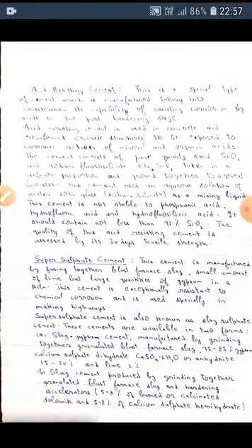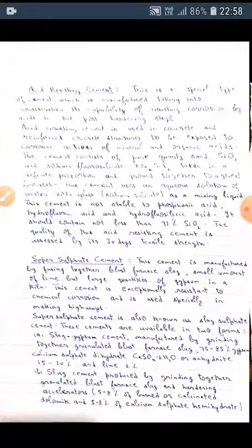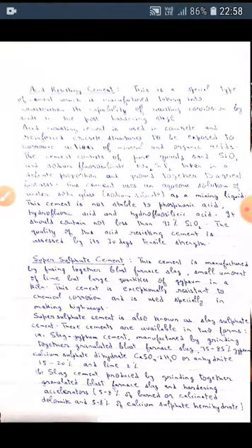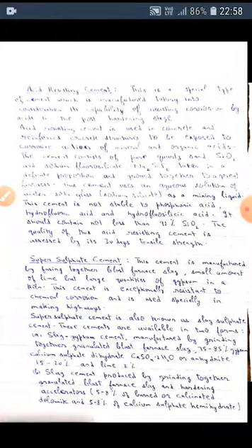The second form is known as the slag cement without clinker, produced by grinding together granulated blast furnace slag and hardening accelerators, that is 5 to 8% of burned or calcinated dolomite, and 5 to 8% of anhydrite or calcium sulfate hemihydrate.